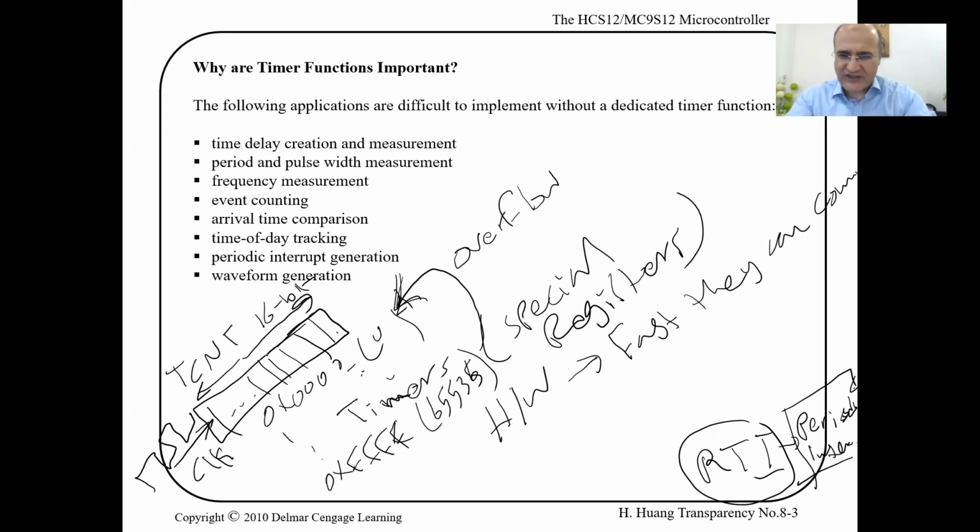If we know how fast they count, and the starting point and end point of counting, you can use them to time. You counted 1,000 times, and every count was at 1 megahertz increment frequency, then you had 1,000 microseconds, and so on.